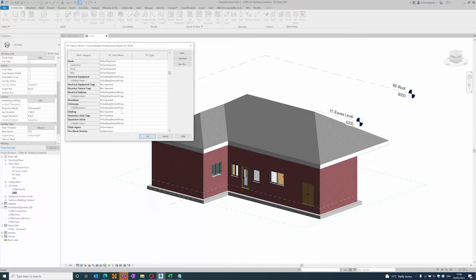Some more examples of this, if we scroll in a little bit further, are things like ducts. A flexible duct is an IFC duct segment, but its subcategory, or IFC type in this dialog box, is flexible segment. If we have a look at a standard duct, we can see that it's also an IFC duct segment, but it's not subcategorized because it's just a duct. This can be very confusing to begin with, but it's important that you understand what this means in reality and how, dependent on what version of IFC you're using, this can be very different with regards to the outputs.